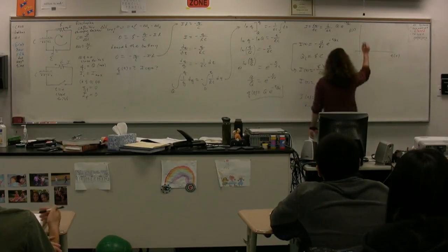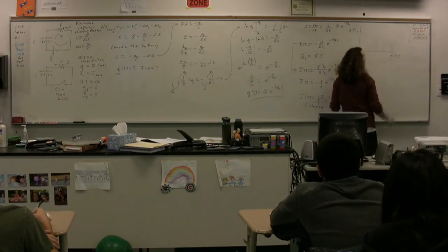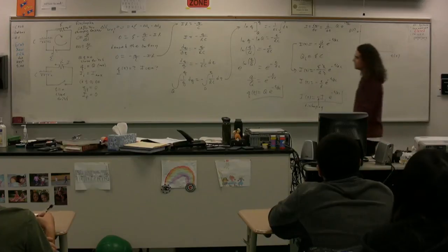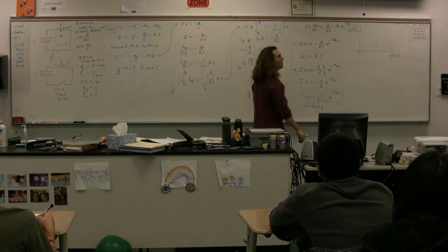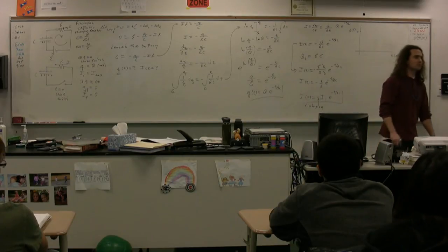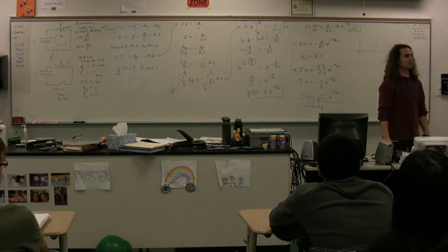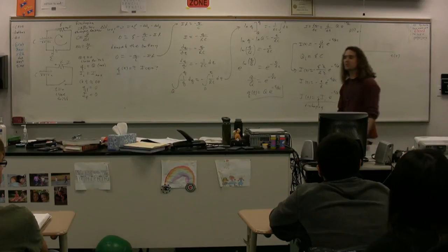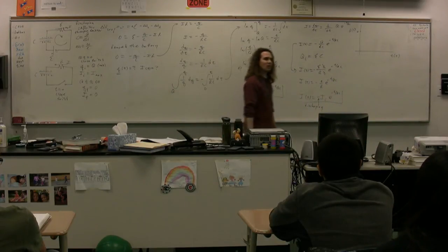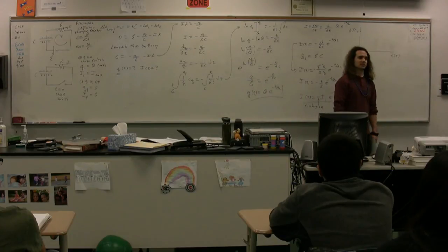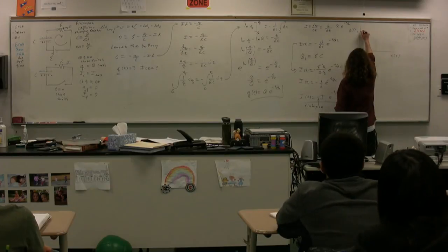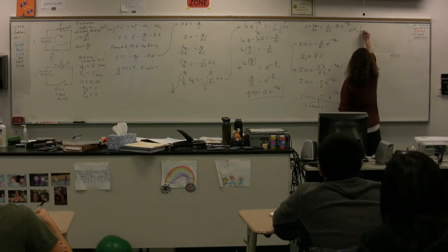That's our initial. And where does it end? The charge final. Discharging the capacitor through the resistor. Zero. So it ends at 0. What does it do in between? What does Q times e to the negative t over RC look like? Show me with your hand. Right. You all know, you've done this many times, it's going to look something like this.